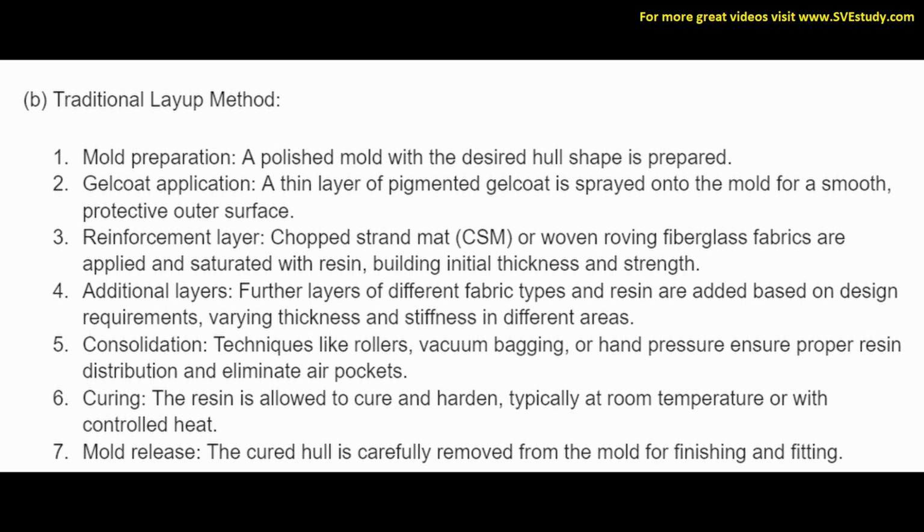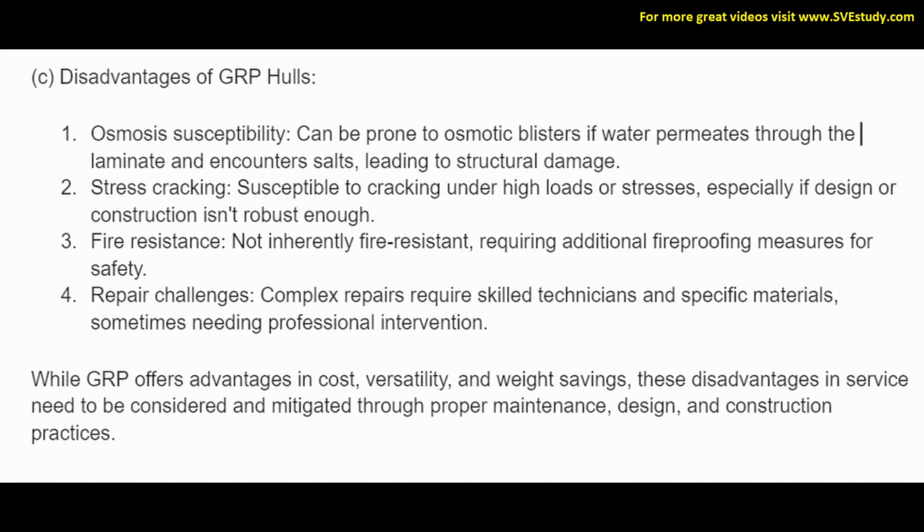Consolidation. Techniques like rollers, vacuum bagging, or hand pressure ensure proper resin distribution and eliminate air pockets. 6. Curing. The resin is allowed to cure and harden, typically at room temperature or with controlled heat. 7. Mould release. The cured hull is carefully removed from the mould for finishing and fitting.